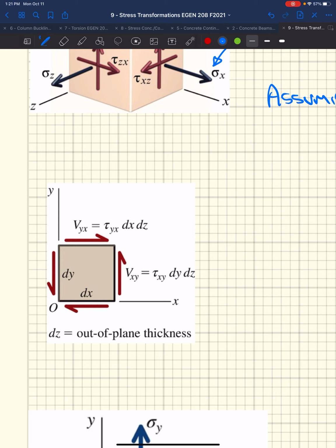We went through that equation to figure out our maximum shear stress. We applied it on one side. And then based on equilibrium, we know that the sum of the forces in the y direction has to equal zero, so these two have to be equal to each other. We also know, summing the moments about the origin point 0, that this block can't be twisting off into space. So that results in these equal and opposite forces on the top and bottom as well, trying to twist it the other way.